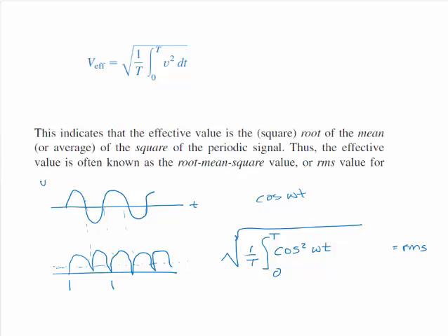It turns out, from the circuit I was showing you on the previous page, that if I'm dealing with RMS values, the power is going to be I squared R, for example, which is I RMS, the root mean squared value, squared times R. This gives you the RMS power, which is the power dissipated in the resistive part of the load.